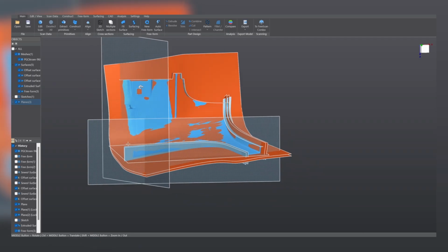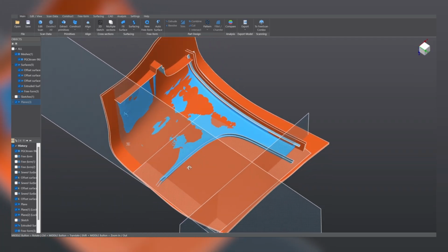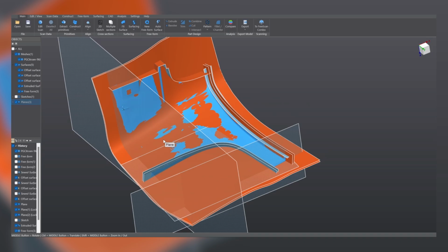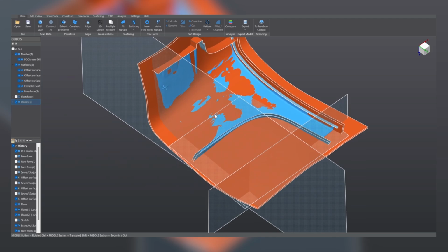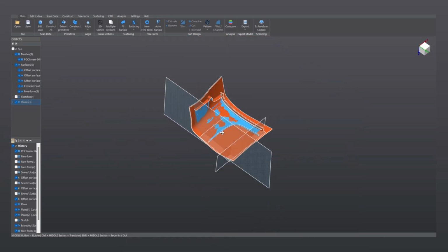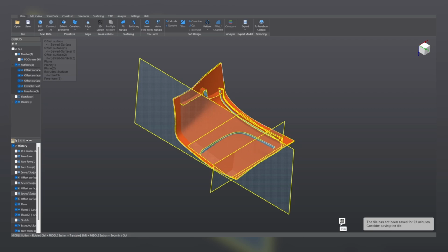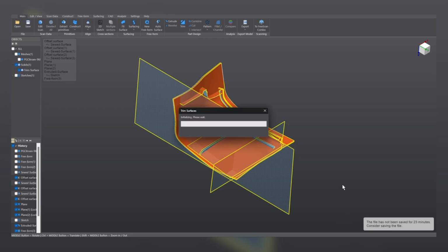And now we have all the surfaces and planes, all the features, to close solid, and so obtaining the shell of the mesh, which is going to result in a solid body. And in order to obtain that, let's hide the mesh. Let's select all the surfaces. And we are going to click on this small button over here, which is trim. Now the software will need some time to compute all the intersections between all the surfaces, and we are gonna continue later.